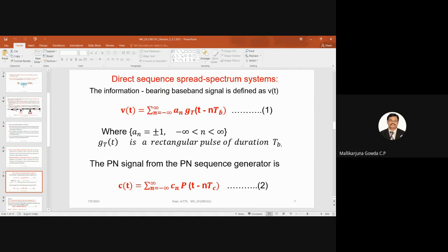Why am I shifting this and multiplying? I said one code word. I have taken here an example of 5 bits, so you will be able to say what the bit duration is out of those 5 bits. If I say it is 5 T_b, then each bit duration will be 1 by 5 of that, and the next bit follows. Hope you are getting that point. Able to visualize those rectangular pulses: negative pulse, positive pulse, negative pulse, positive pulse, negative pulse. You can think of that with respect to my example 0, 1, 0, 1, and 0.